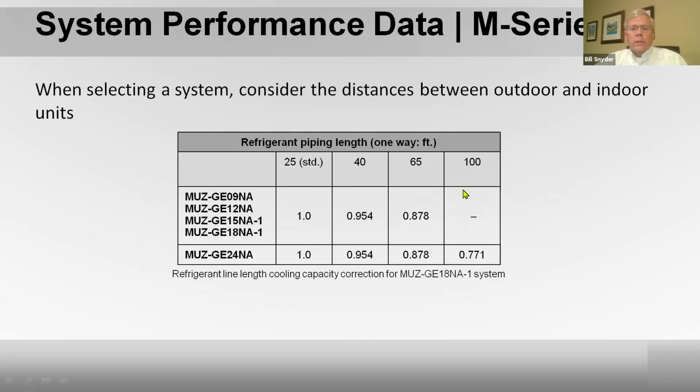Consider the distances between the outdoor and the indoor unit. Like I said before, it's recommended that you have a 16-foot minimum. We certainly can operate with less than that, but they might hear some noises from the outdoor unit the closer the line set is to the indoor head.